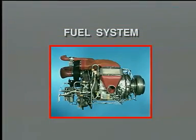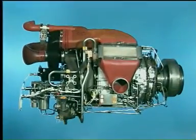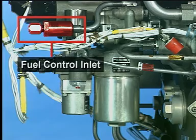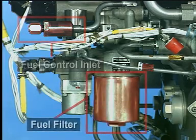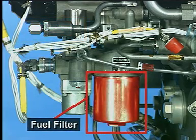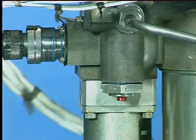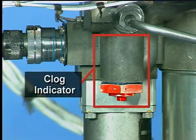Fuel system. The fuel supply from the aircraft is delivered to the fuel control unit inlet. It is filtered by a fuel filter installed on the fuel control unit housing. The filter condition is monitored by a clog indicator.